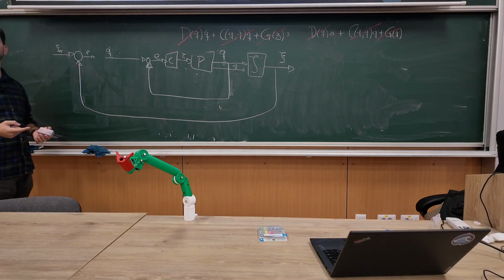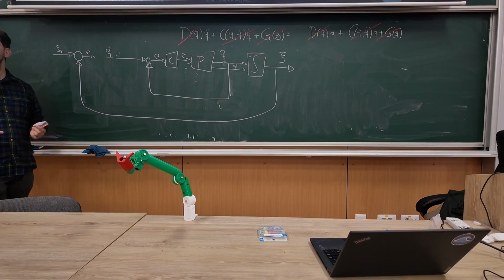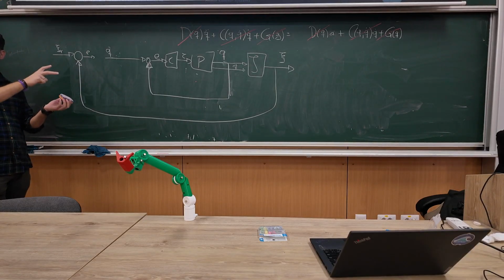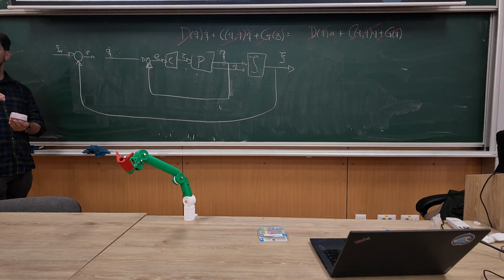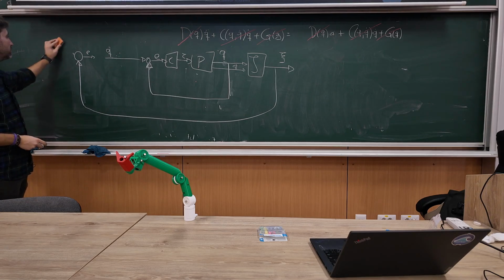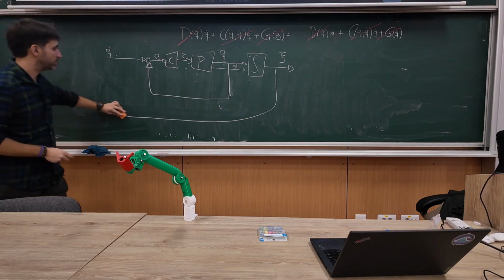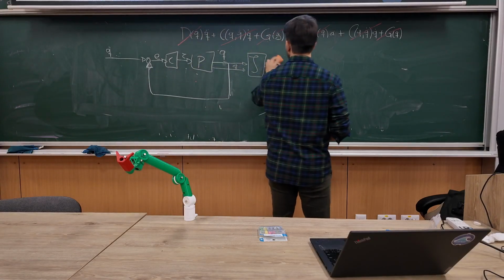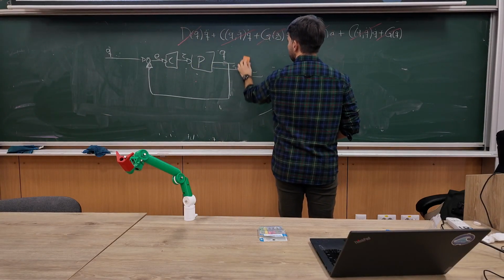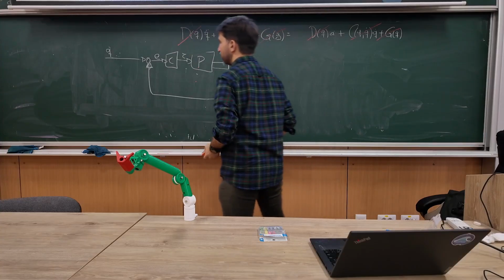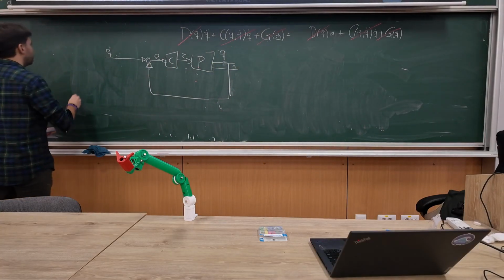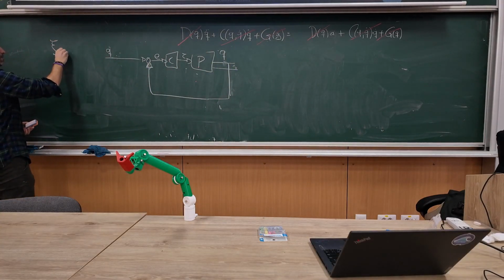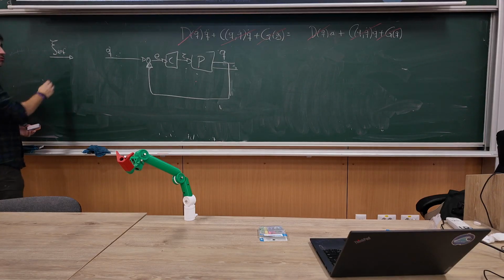How did we do it for the end effector pose? I started with pose and I calculated joint coordinates, with the inverse. If we know the velocity vector, with the inverse Jacobian, we can see what the joint velocity is. Exactly. So I do things at the beginning, not at the end. That's the message. So I have a Xi reference and I want to convert that to joint